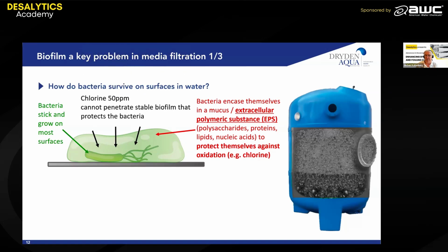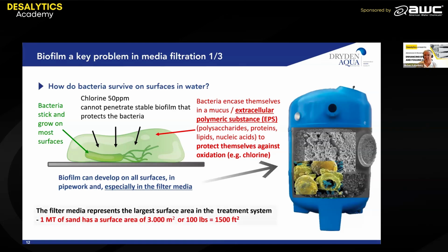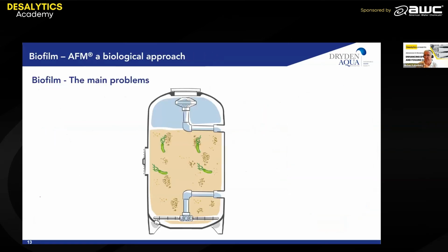These lead to biofilm formation, and you want to control it by using chlorine as a disinfectant or killer of the bacteria to avoid the biological growth. And as many of you may already know, by using chlorine in continuous dosing, bacteria can adapt, and you can have the regrowth of bacteria or biofilm, which may lead to even higher biofouling potential or growth in your membrane system. Yeah? So what happens in a sand filter?